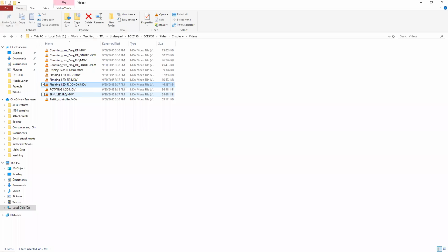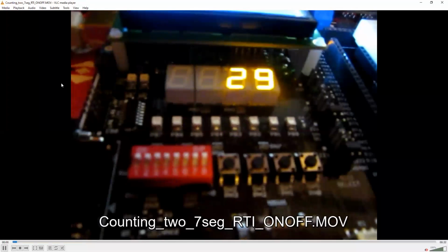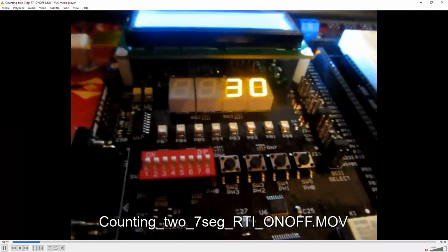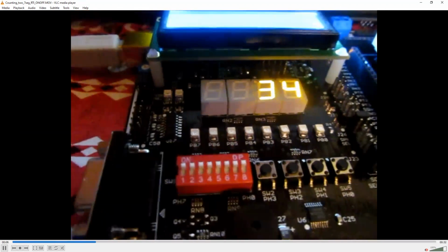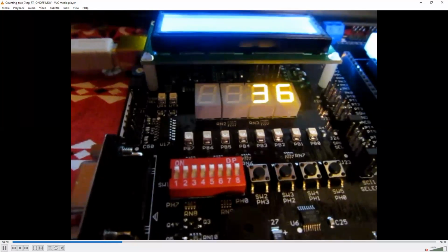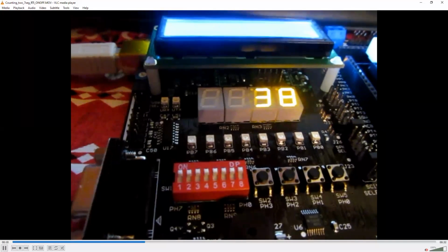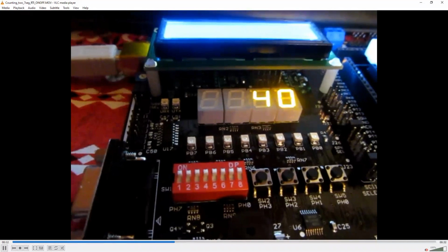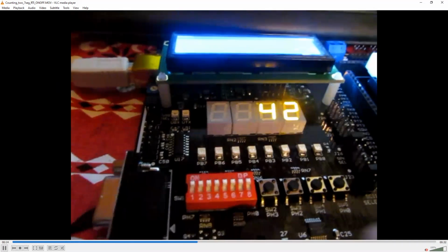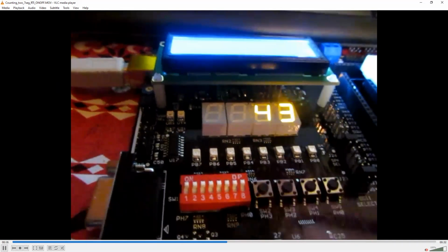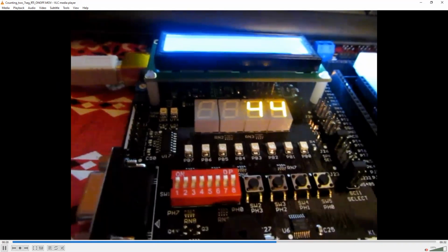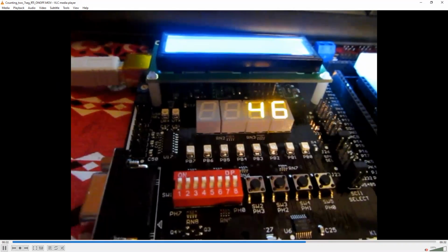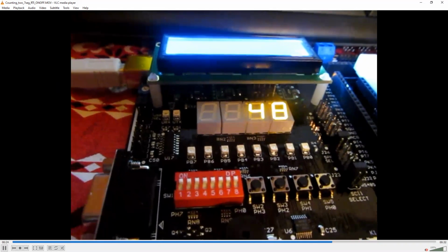This is counting, yeah, this one. Look here, guys, it's counting every 1 second using RTI, because counting is done by RTI. It is not done by IRQ, right? So see, 37, 38, 39, and then I have to press the button. When I press the button, I'm going to disable RTI. I press again, enable RTI. Is that okay? I want to do something like that.